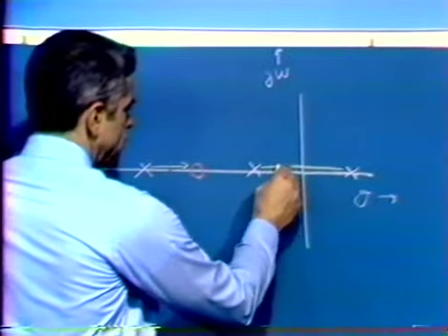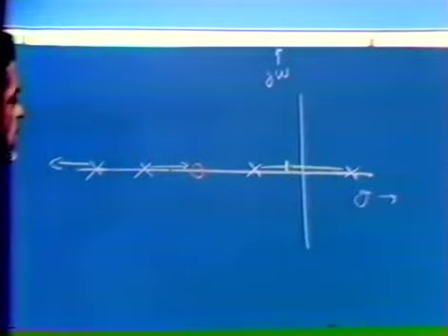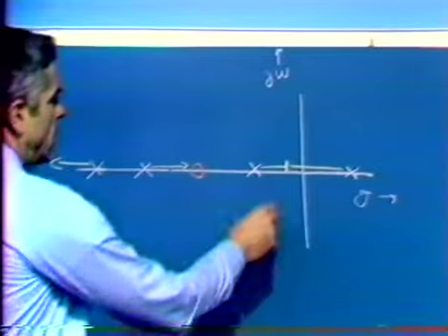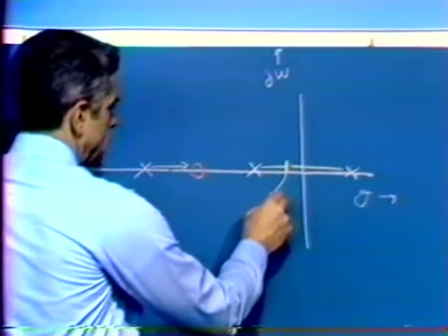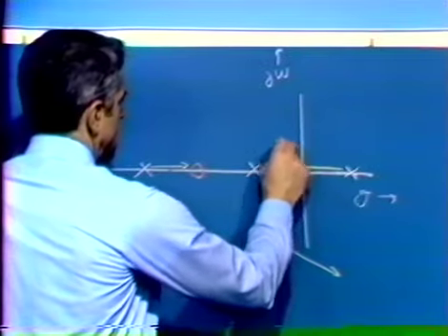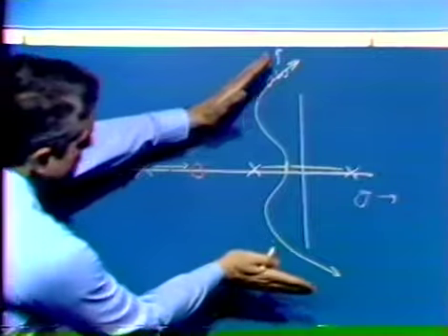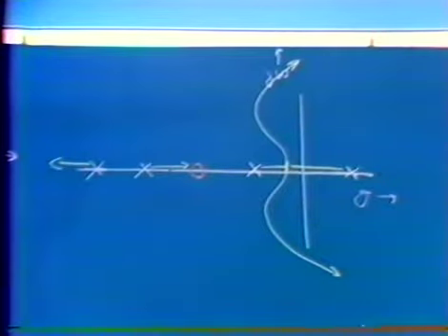So these 2 branches meet at a point somewhere in the left half plane. And again, depending on the exact spacing involved, we might end up with a diagram possibly that did something like so. Eventually the branches are going off, making angles of plus and minus 60 degrees. The third branch, of course, going off at minus 180 degrees.